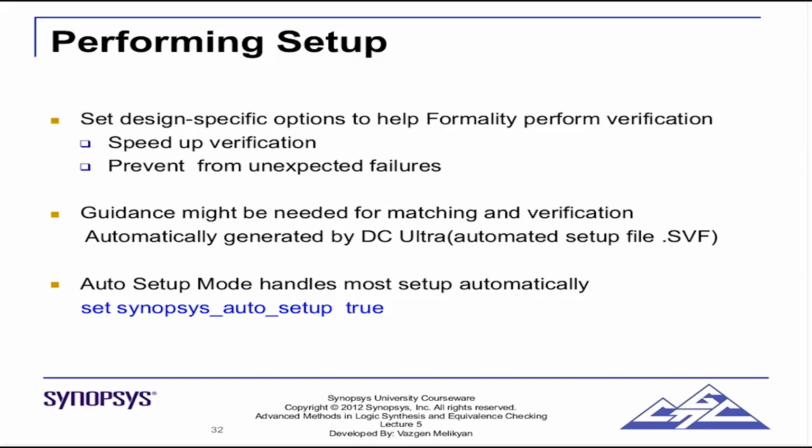Although the idea is not to get lower area like Design Compiler. The Formality synthesis engine is just aimed at providing a gate level representation, not optimized for either timing or area. It is just for showing you the functionality. So the synthesis engine inside Formality is entirely different from the synthesis engine inside Design Compiler. But there are variables which control some kind of functionality. For example, there is one variable which controls the value of the registers at initialization. Now these variables you might have to tweak before you can get the setup ready.